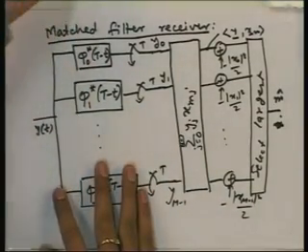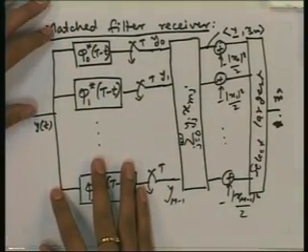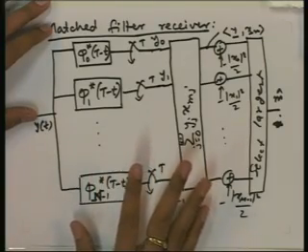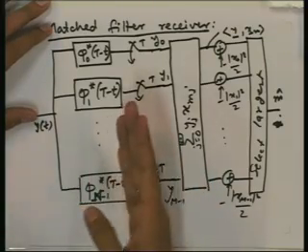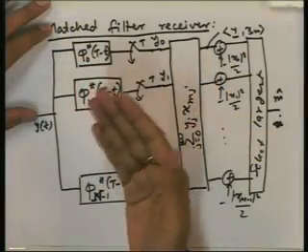Then we have also seen that we can demodulate differently, using matched filters matched directly to the signal set instead of the basis signals.